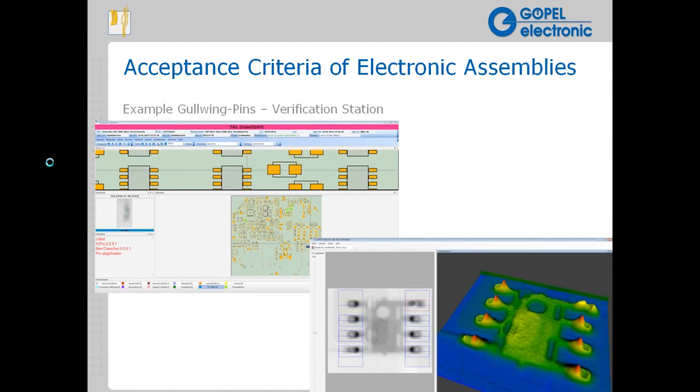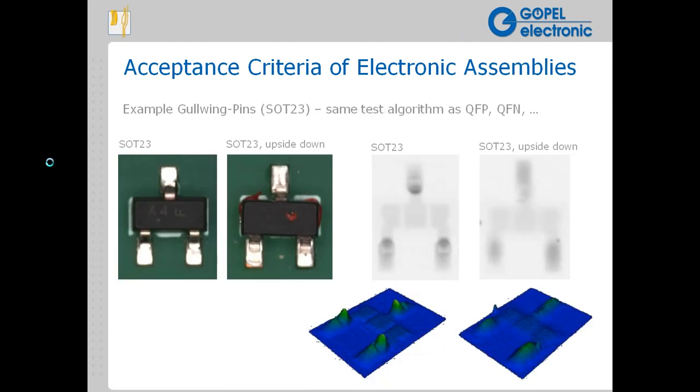In the left X-ray image, for the SOT23, you can see a very healthy heel on the solder meniscus. And on the right, of course, you see a very poor solder joint, and that is further illustrated in the top view itself. This is actually a case of an inverted device. This device is glued down to the board, but it was inverted during assembly, so there's no solder joint whatsoever there. From the optical standpoint, that's not all that obvious. It would be made more obvious from an angle view with AOI, but again, X-ray brings even more information to the table.